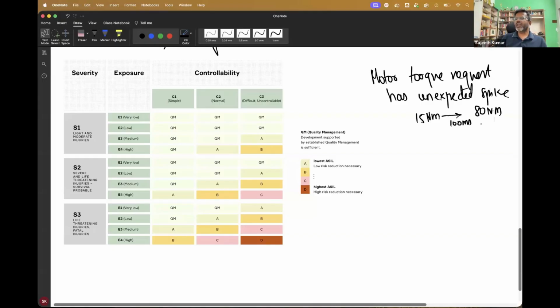You have a condition where you have done everything properly. So the user is suddenly given full throttle. I mean, it can happen. In 100 milliseconds, the motor was giving 15 Newton meters of torque, and now suddenly it has to give 80 Newton meters. Why? Because you directly connected your throttle to the motor control unit and suddenly he gives throttle, it has to deliver this. Now you think and tell me if this is happening. This is a failure. The function is not supposed to behave like this, but in case it behaves like this,